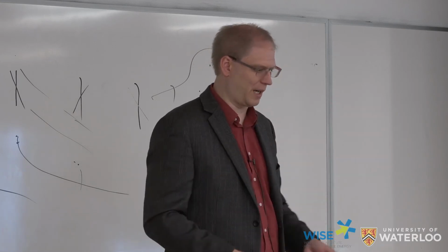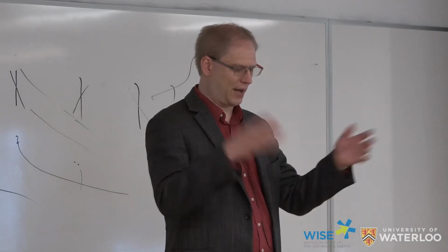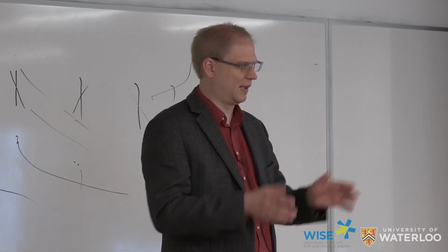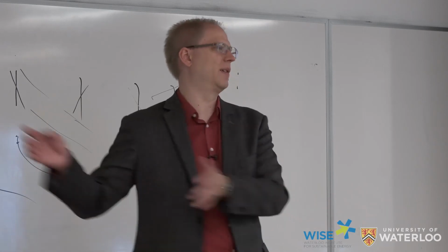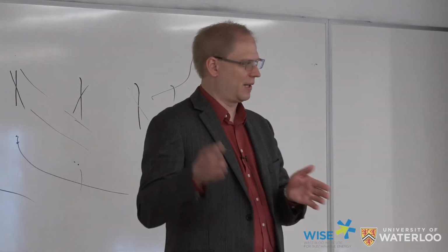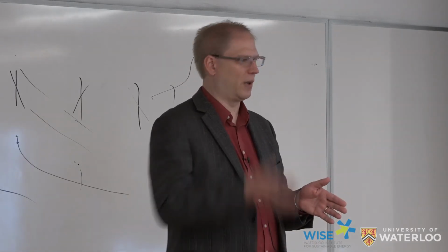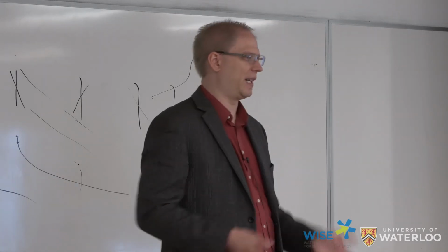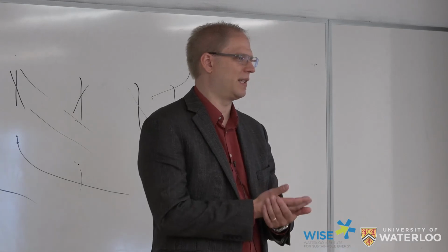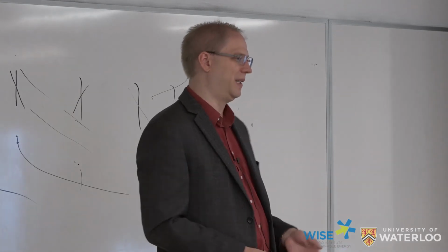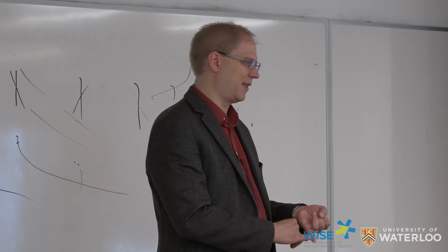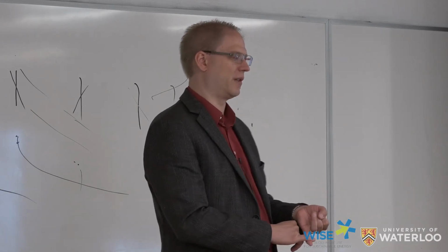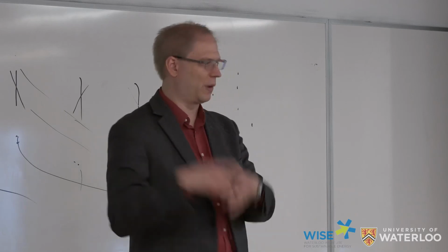So what we're doing now is we parameterized the 1,000 inputs in FAST, we narrowed them down to about 45, I think, that are probably the most sensitive, and we're propagating those through to figure out what's the top 5 or top 10, or what's the real break point beyond which they're all kind of the same. And we're doing that now, and I have a journal publication that we're working on to answer that question. So then I can tell you, for a given turbine, here are the top 5 parameters or whatever it is for the inflow, and here are the top 5 or so for the structure that are really driving the loads more than the others.